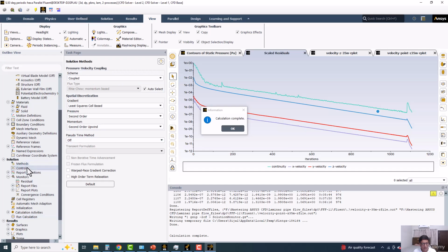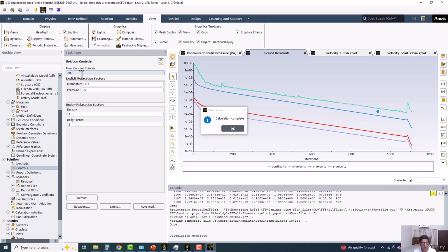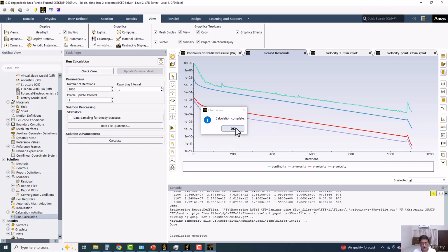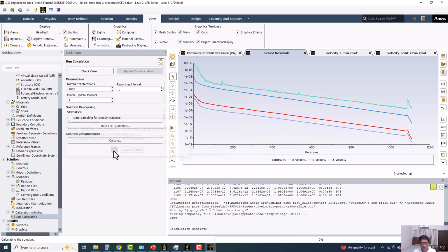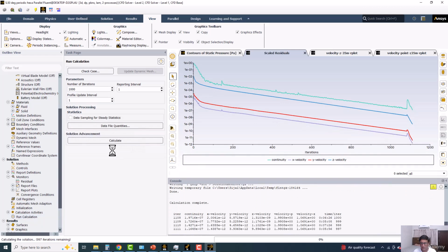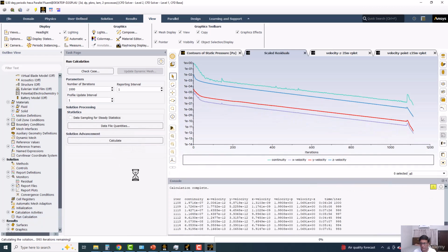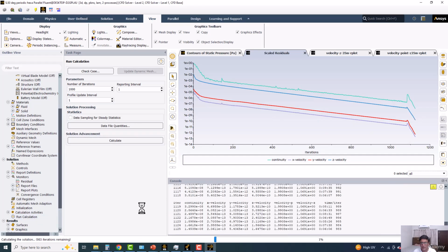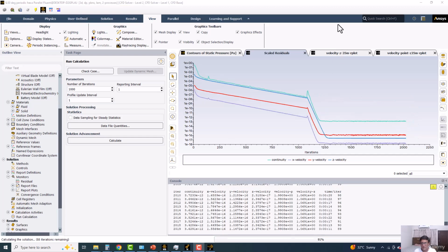Make it off, and then in the controls you can go from 200 to around 2 million. Let's make it at least 2000, which is needed. So you can try with 2000. If not, then you can go back to 200. I used to use that method in the past, and this is the best method actually for converging the solution. Okay, try this one.